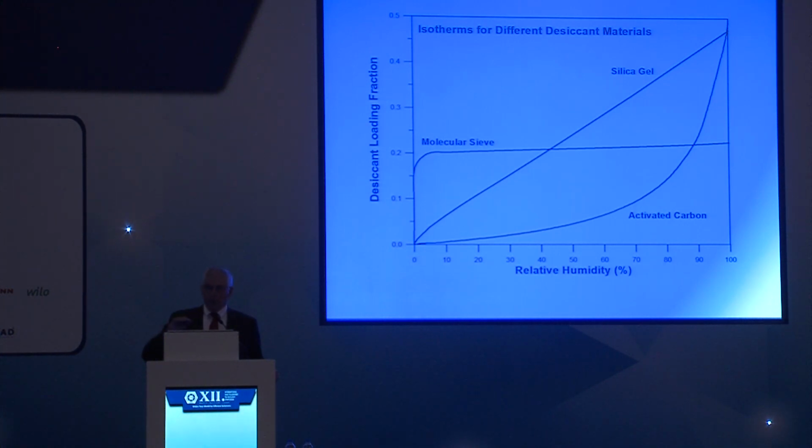So you can think of molecular sieve on that surface, there's probably 1 or 2 layers of water molecules on that surface. Therefore, it's a very strong absorber. And the one I was mentioning for the type 1M is somewhere in between. Does that make silica gel better than molecular sieve? No. It depends on the application that you're going to be using it for.